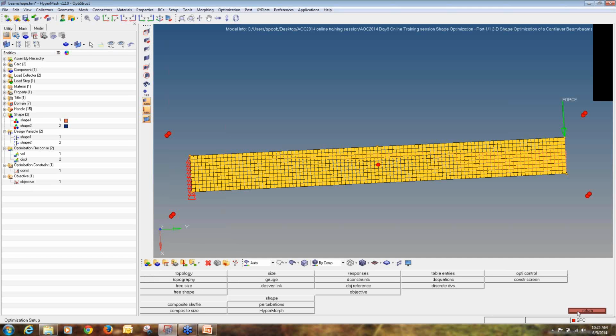Now we will define a shape card. So only the displacement and stress results are available in the H3D file by default. In order to look at the displacement and stress on top of the shape change that was applied on the model in HyperView, a shape card needs to be defined. So if you want to see the displacement value while seeing the shape change both in one file, you have to define a control card.